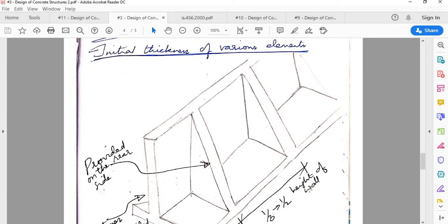The second thing is, due to the soil pressure that is incident on the wall, there is a chance for the wall to detach from the counterfort. So this junction should be strengthened. That strengthening is done by introducing horizontal stirrups between the vertical stem and counterfort.